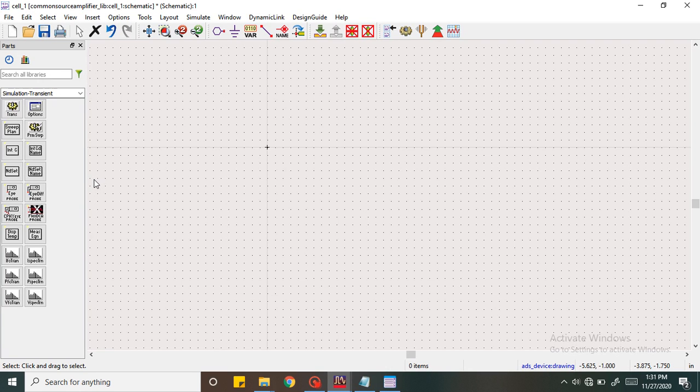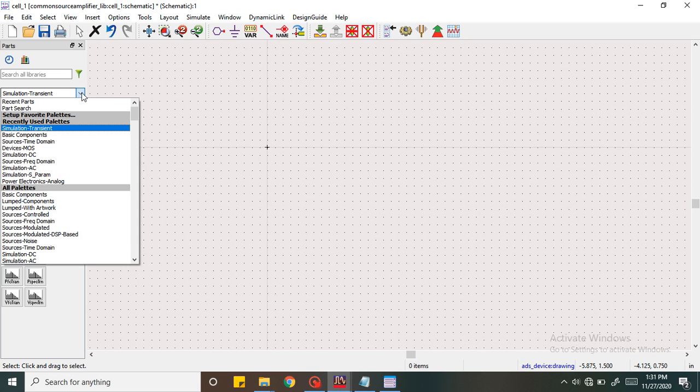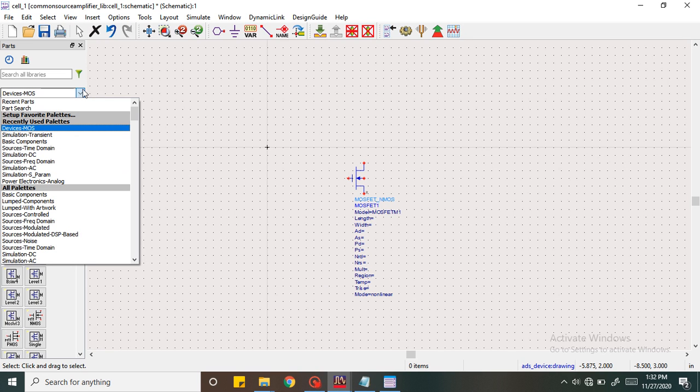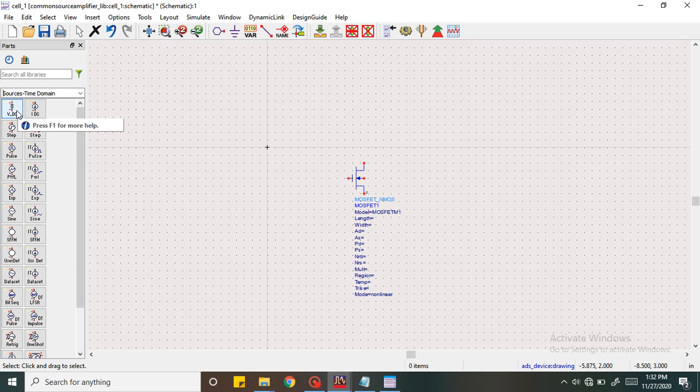In this video, we are going to see about the designing of common source amplifier. So let's get started. Initially, we take the NMOS transistor from devices MOS. For the common source amplifier, we are taking an NMOS transistor, and we are taking the sources from sources time domain. For VDD, we are taking VDC.